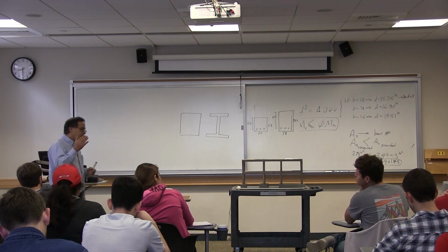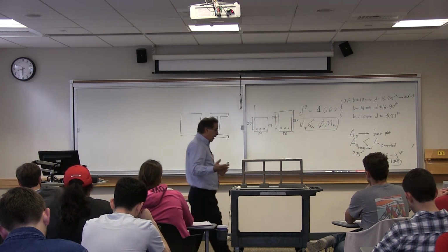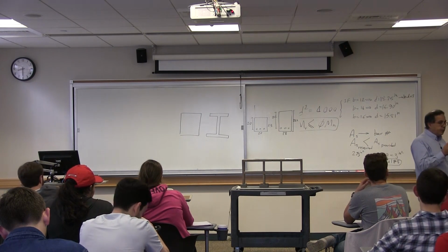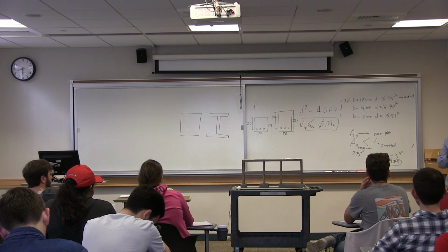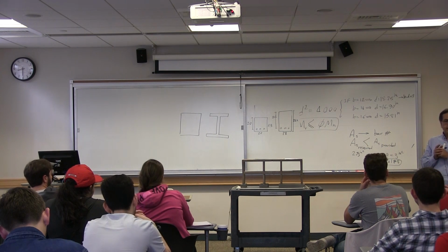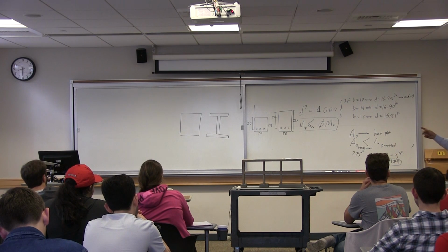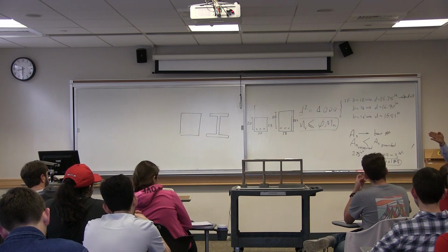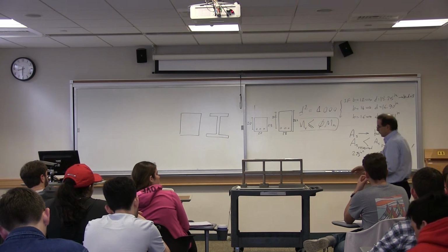So for instance, I just give you one guideline. Your beam is better to be not narrower than your column. When you make beams narrow and deep, your beams become narrower than the column.